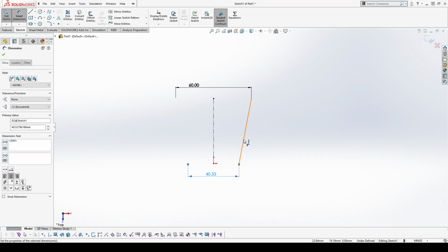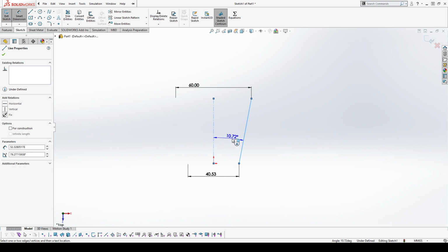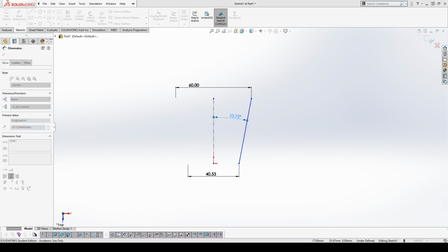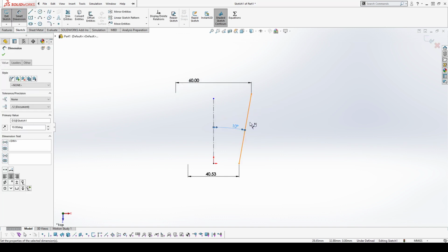Same thing goes for angles. I just clicked on that line, and I didn't even click on the center point. It automatically was like, hey, I'm dimensioning off of this construction line. I'll keep plopping in dimensions off of that. So maybe the draft angle on the side of this cup is 10 degrees. And you can see that now the D right next to my cursor changed into an A. So it's an angle dimension off of that center line. And to exit out, I just press the escape button, and the A and the construction line drop off. So now it's just back to normal dimensions.